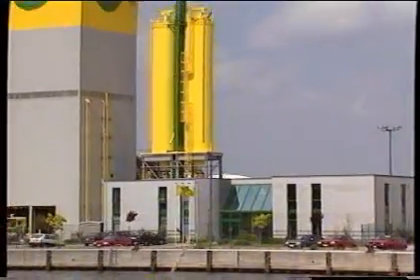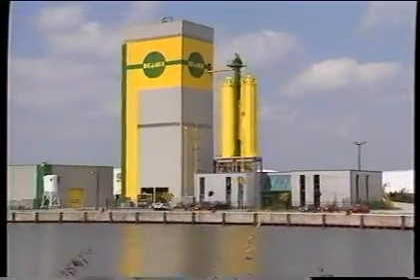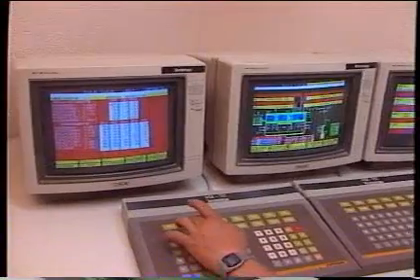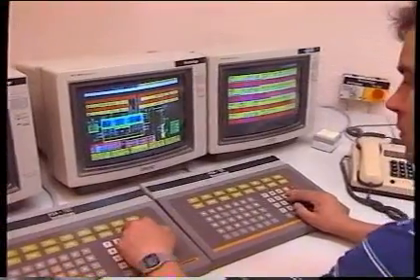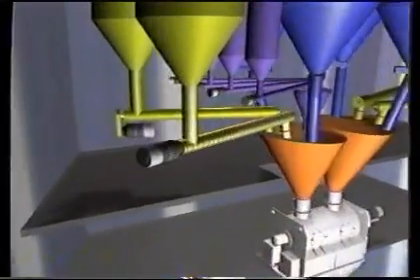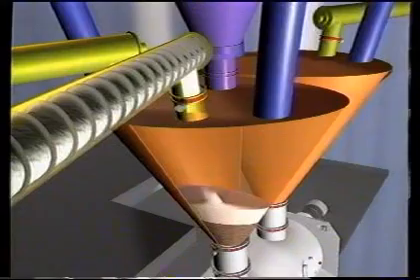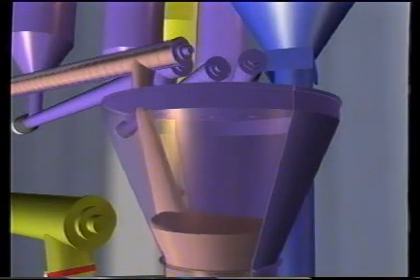Follow us into a modern computer-controlled dry mortar production plant as constructed by the m-tec Plant Engineering Department. So, how is dry mortar made? There are different storage silos for sands, binders and additives. The sands and the binders are weighed separately in high-volume scales and the additives in high-precision scales for small portions.